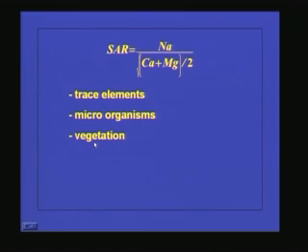And another important thing is the vegetation, the type of crops or plants present in the system, because if the plant is able to take up a lot of nitrogen and phosphorus, and if it requires a lot of water, then that type of plant or vegetation is more preferable for land treatment.